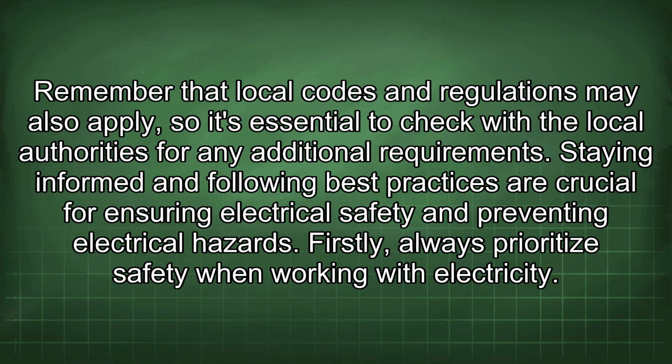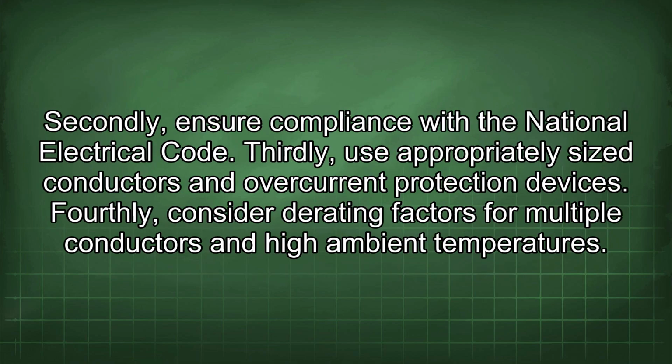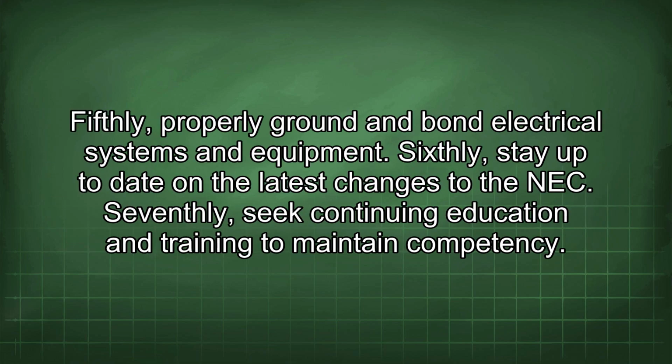Firstly, always prioritize safety when working with electricity. Secondly, ensure compliance with the National Electrical Code. Thirdly, use appropriately sized conductors and overcurrent protection devices. Fourthly, consider derating factors for multiple conductors and high ambient temperatures. Fifthly, properly ground and bond electrical systems and equipment.